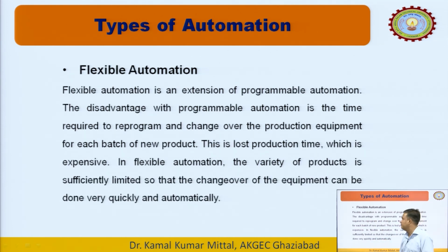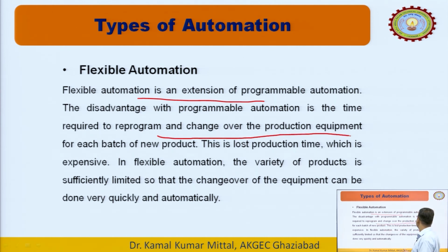Then comes flexible automation. Flexible automation is an extension of programmable automation, or we can say an advanced automation system. Advanced means that the disadvantage we had in programmable automation, we get the advantage of it in flexible automation. The changeover time is the time required to reprogram and change over the production equipment for each batch of new product.